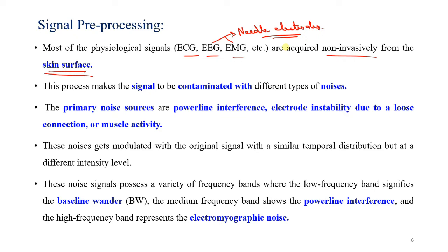Okay. So when you are putting any surface electrodes onto the surface of the skin, what is happening? Suppose this is the skin surface, and over here you have the electrodes which are collecting the data. Now if you put this electrode over the skin surface, the potential generated in this area will have some contribution to the signal being sensed by these electrodes. Okay. So we are getting an average of a wider area.